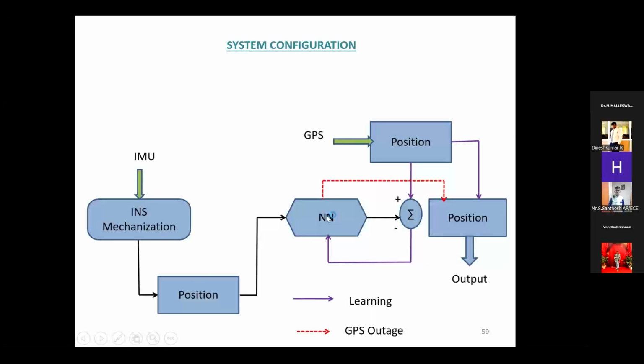The trained values are here also from the Jordan type neural network, but the algorithm you are using for training is PSO. Now these GPS values can be compared with the INS, and the error, target value minus trained value, will be obtained as a corrected INS value, which can then be available for navigating the object even though the GPS is on outage. So this is the way you do intelligent-based navigation using the system configuration.